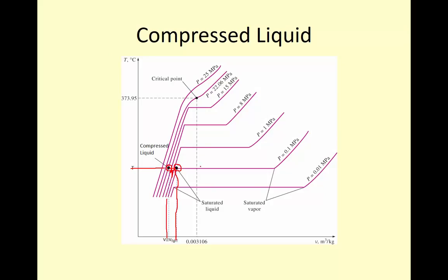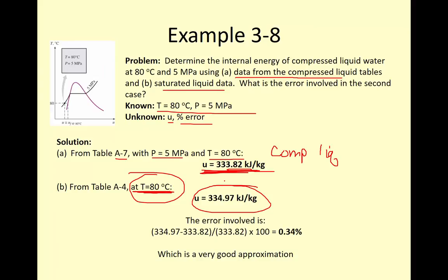to this diagram on a TV diagram, that's where we're making the approximation. So if we want to know the specific volume for something at this temperature that's a subcooled liquid, then we have to approximate it at the temperature of a saturated liquid. Okay, we don't use pressure, because at the same pressure it's actually going to be this value up here, because that's the constant pressure line, and it just really messes things up. So again, only look at it at the same temperature.